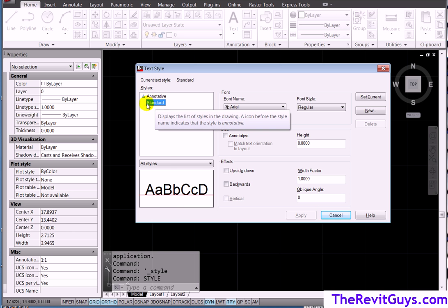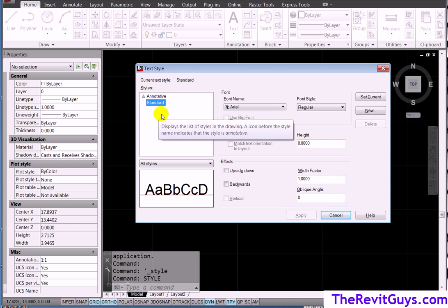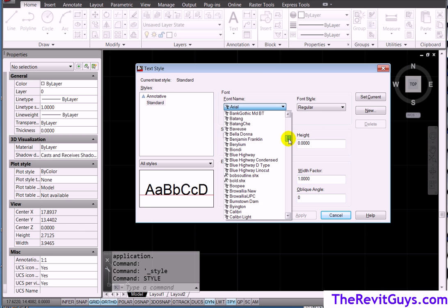So now the font that looks like Arial, it needs to be Bob's Big Font. So what we're going to do is grab this here, and we could make a new one if you want to do that. Or you find the font that's not showing right. Maybe it's the standard one. It's supposed to be Bob's Big Font, but maybe AutoCAD has swapped it out. So I'm going to come down here. Now another little tidbit. When we reopened, if you've turned off the font alt, AutoCAD may come up and tell you that it can't find the fonts, so it'll warn you. So you'll get a little bit different interface when you come up. Now I'm going to come in here, take the standard one, drop this down and say, let's go use Bob's font. So we come on down here.